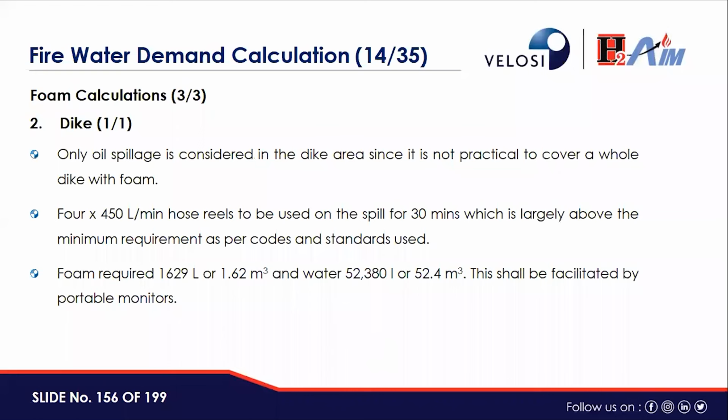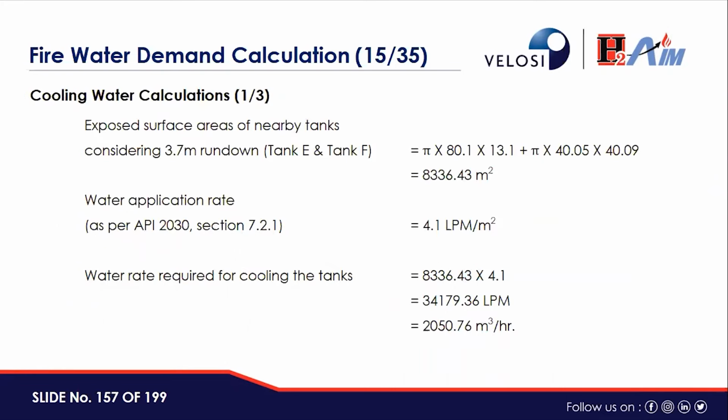Similarly, for dike, only oil spillage is considered in the dike area since it was not practical to cover the whole dike with foam. 450 liter per minute hose reels to be used on the spill for 30 minutes, which is largely above the minimum requirement as per codes and standards. Foam required 1.62 cubic meter and water 52.4 cubic meter, which shall be facilitated by portable monitors.